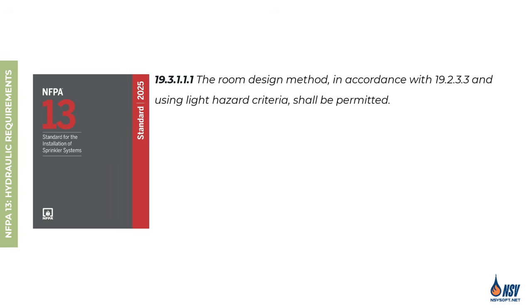As a final note, we should remember that NFPA 13 permits the use of the room design method for residential sprinklers to determine the number of sprinklers in the design area. We covered the room design method in a separate video.